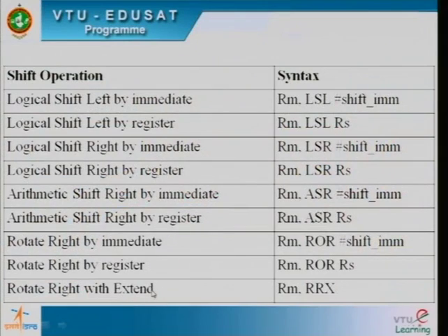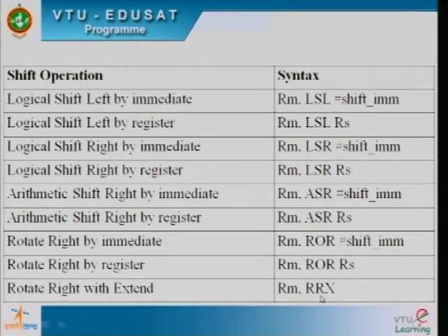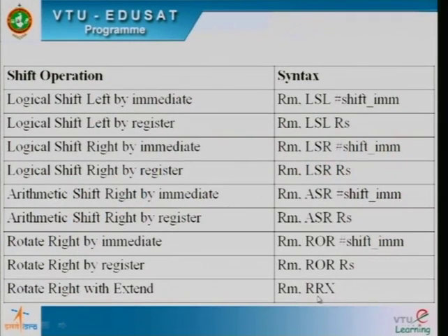Then there is one more option, rotate right with extend. What do you mean by extend, or what is the syntax? Rm, RRX. RRX stands for rotate right including a carry. Extended here means a carry.